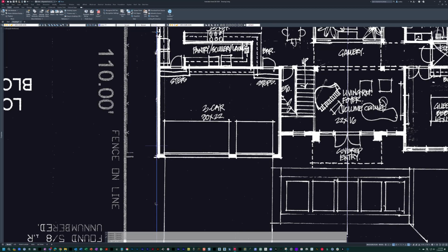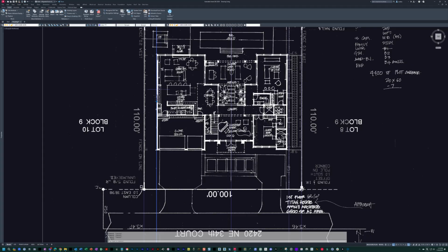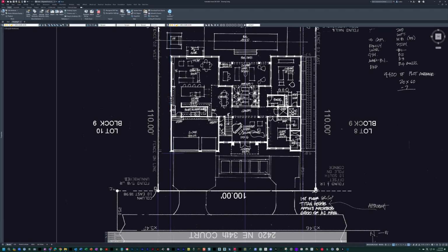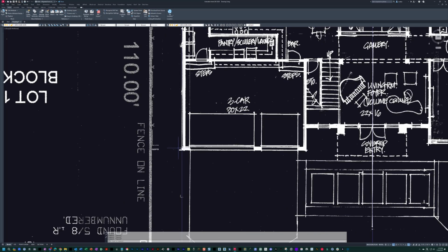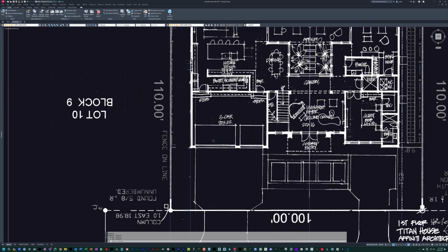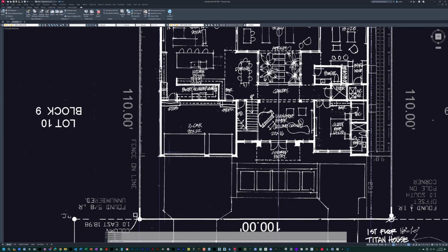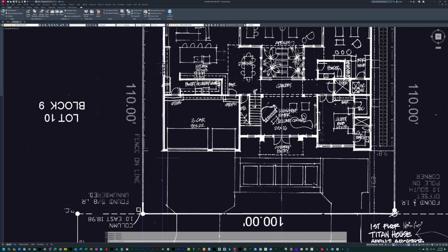I currently have this line, which quote unquote is my setback, but we're going to use that as my exterior wall. Though, just as a rule of thumb, I generally like to start an inch or two off the setback to allow for if we want to add any stone or what have you, or just give me a little bit of freedom so I'm not so locked in, but we're going to maximize it out right here.